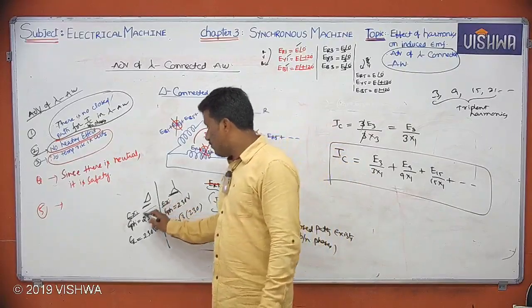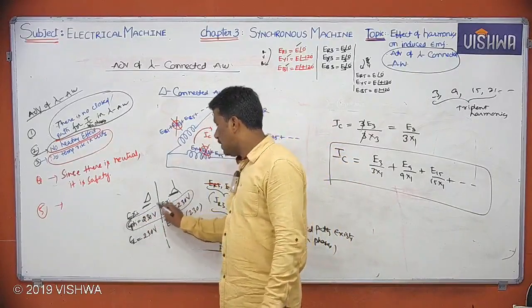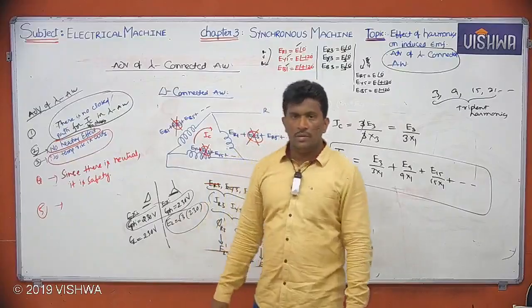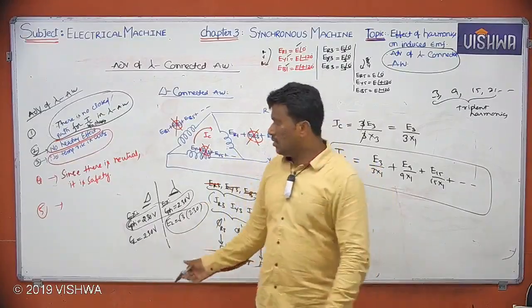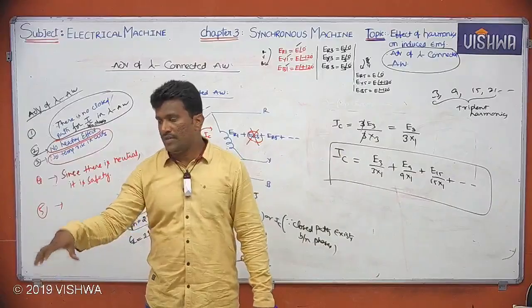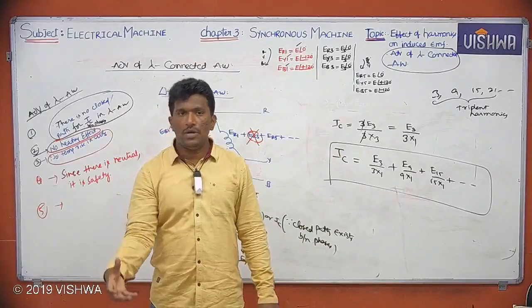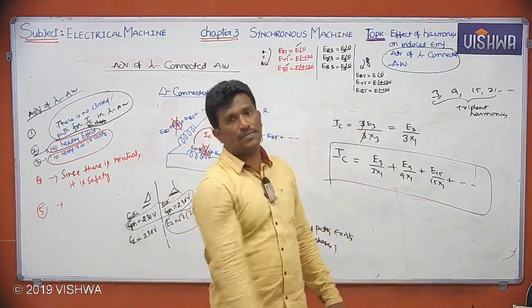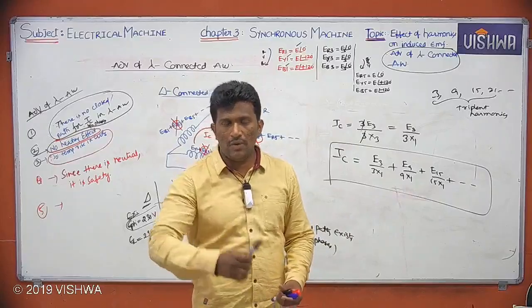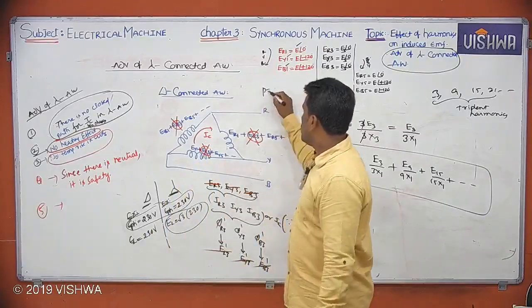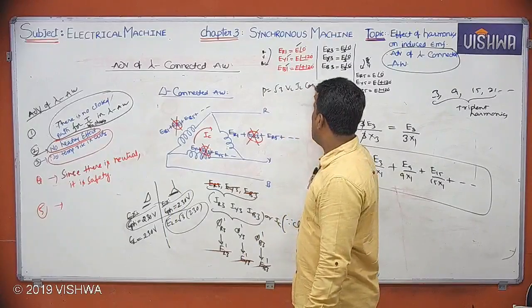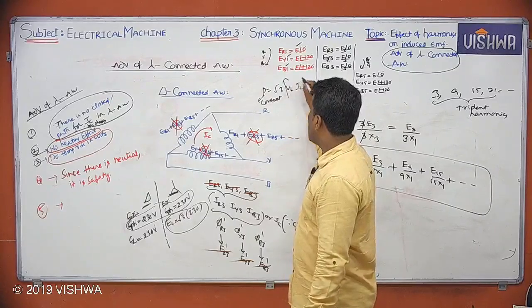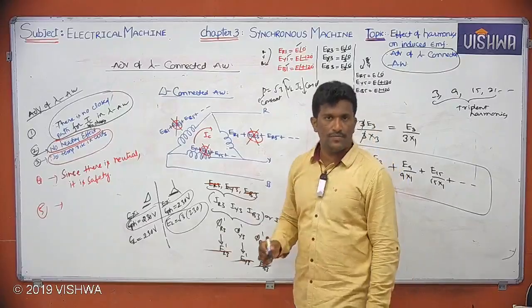So what is the conclusion here? If you take the same phase voltage in star and delta, in star the line voltage is more. Because of that, what is the advantage? It's very simple. After generation, you are giving that line voltage to a step up transformer, so that we will transmit high voltage. If I transmit at constant power, P equals √3 VL IL cos phi, with a high voltage the current will be less, and the loss will be less. That everybody knows.